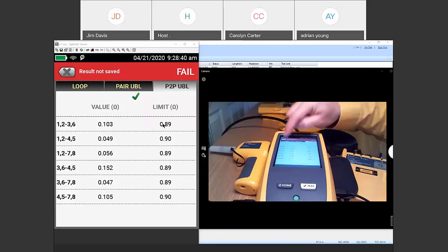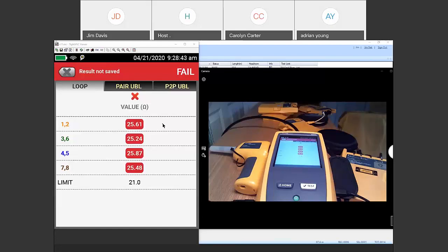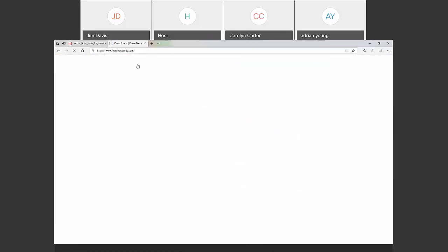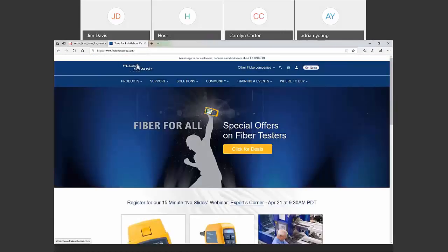But if it shows up as an issue, then the chances are you've actually got a contact resistance issue going somewhere. And I like that. I like the unbalanced measurement for that, not for the PoE issue, but the fact is when you get that call, and we had it a couple of weeks ago, the link is flaky. I test it. It says it's okay. I'm thinking, well, you might have a contact resistance issue. And sure enough, they do resistance measurements, and one of the pairs is completely wackadoodle. Sorry, that's an English term.